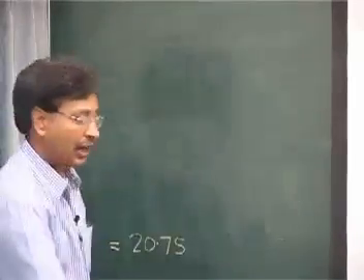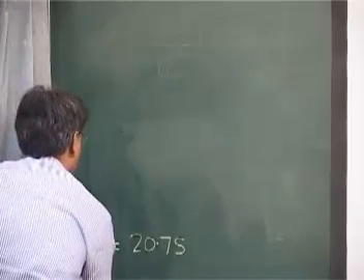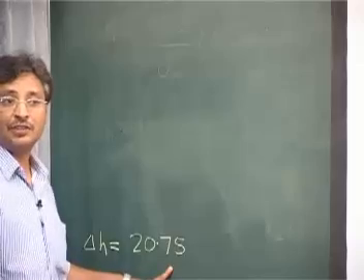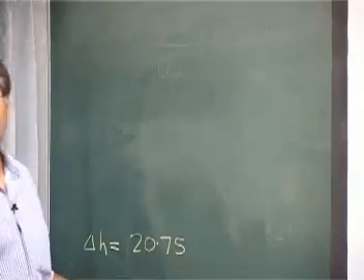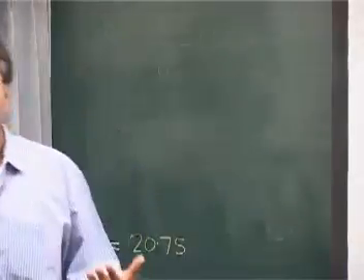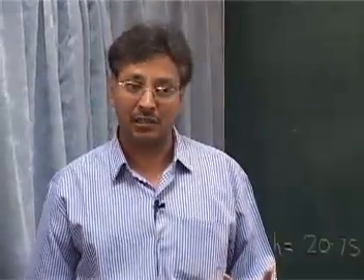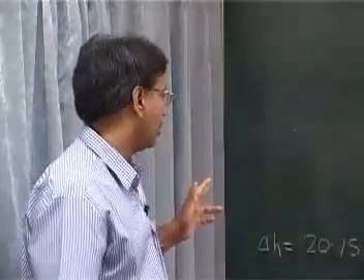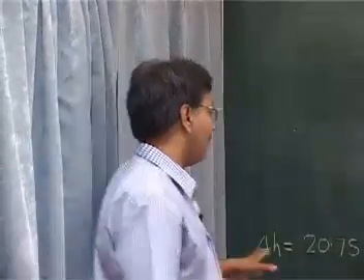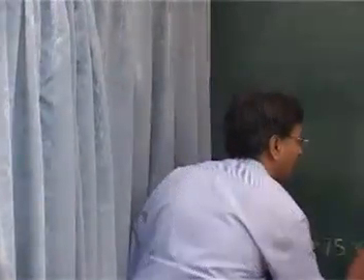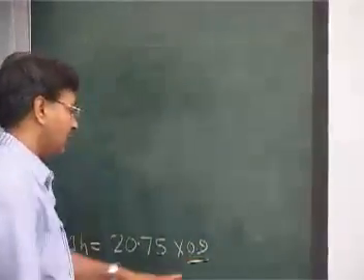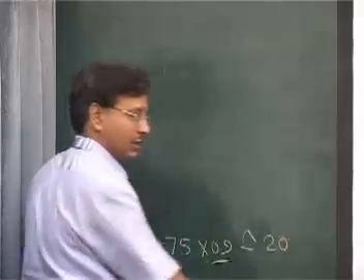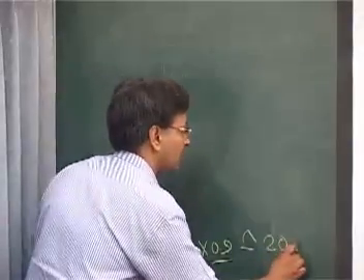The next thing you can write, this was our delta H. We generally correct this delta H for stability, right. We take this as 0.9 in case the conditions are stable. For neutral, we take it as it is. Okay. So in that case, let us say if I multiply with 0.9, the correction for stability, approximately this is 20 meters.